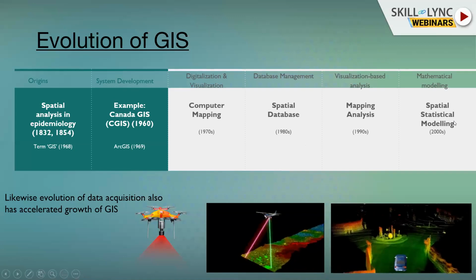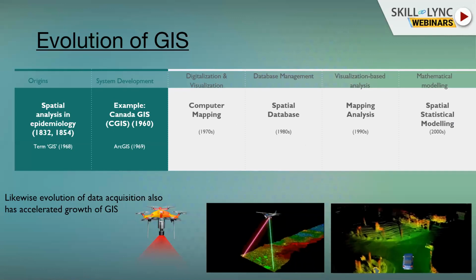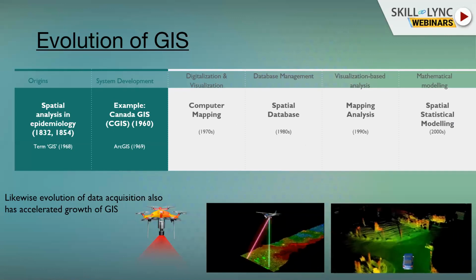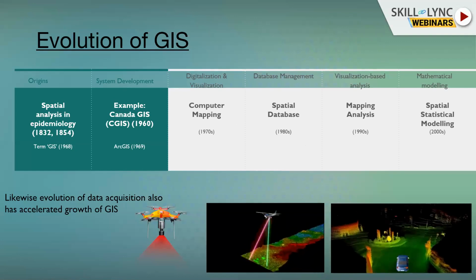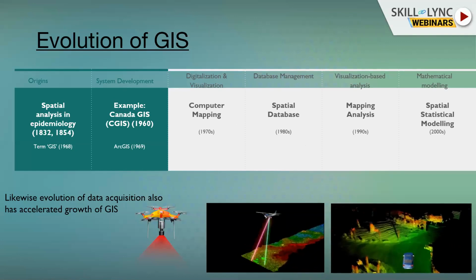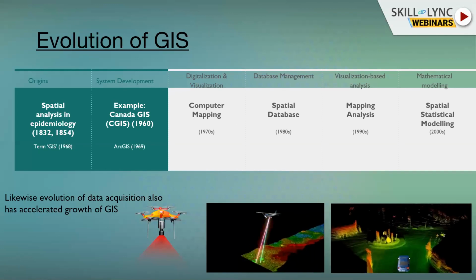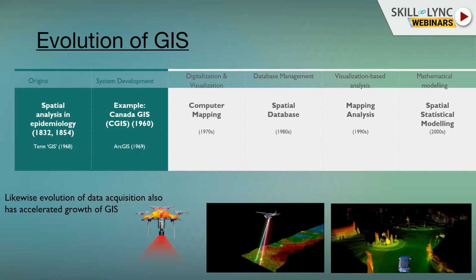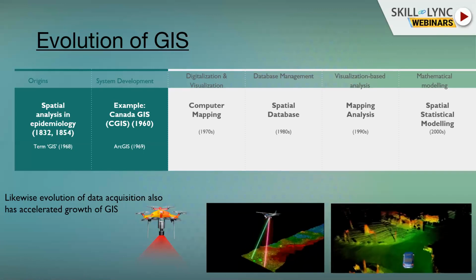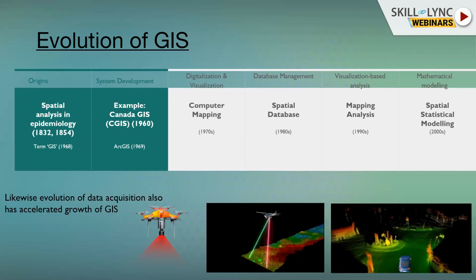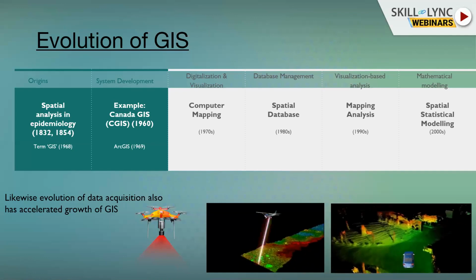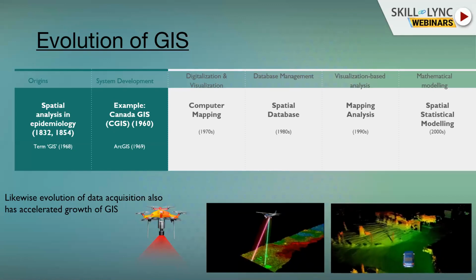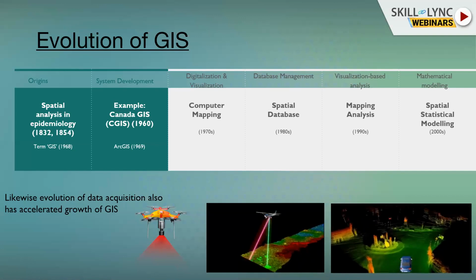I'll tell you a beautiful example. Suppose you are constructing a port, you need to see what changes happen to the coastline if you are constructing a barrier somewhere, right? It will let you know. There are very good mathematical models which tell you what the shoreline change is, how much the siltation will be, where you need to build your groins so that there is no siltation there, and on which extent of the shore there will be more siltation. So that's just a simple example.